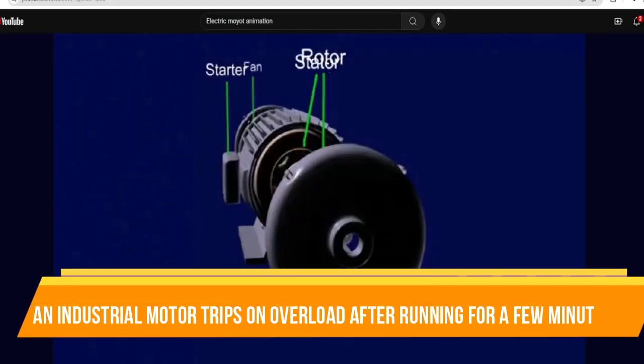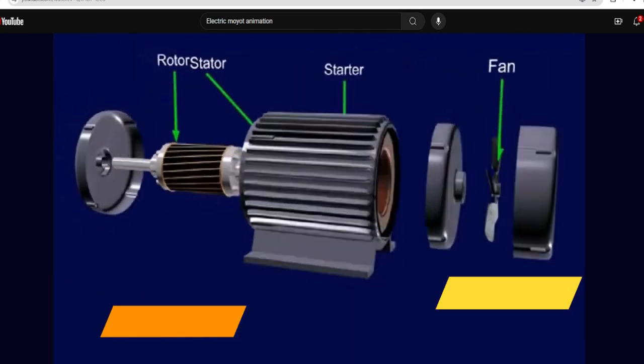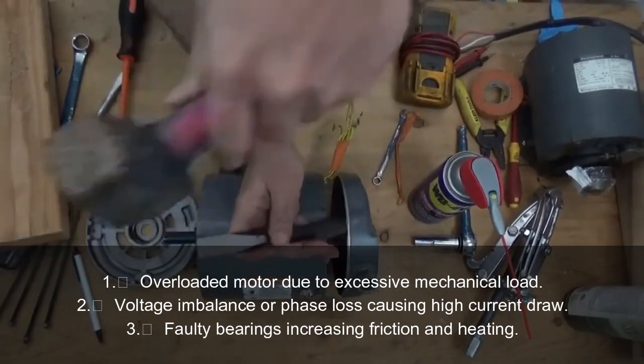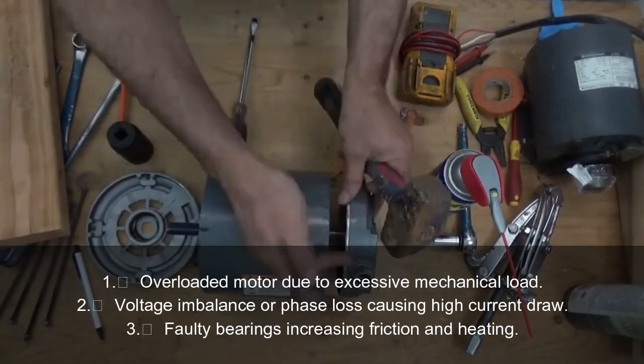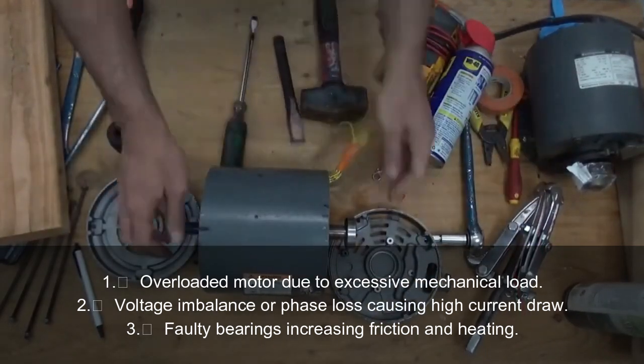Next question. An industrial motor trips on overload after running a few minutes. What could be the possible causes? Answer. Number 1. Overloaded motor due to excessive mechanical load. Number 2. Voltage imbalance or phase loss causing high current draw.